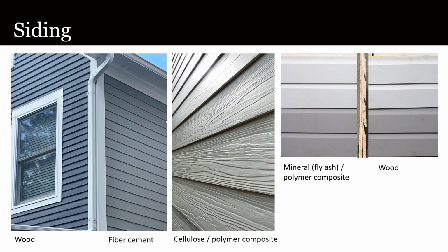Cement board is notably heavier, and the polymer and mineral one has less tensile strength, factors that affect the handling of the material in installation. But they can be less affected than wood by moisture, and can offer better fire resistance.